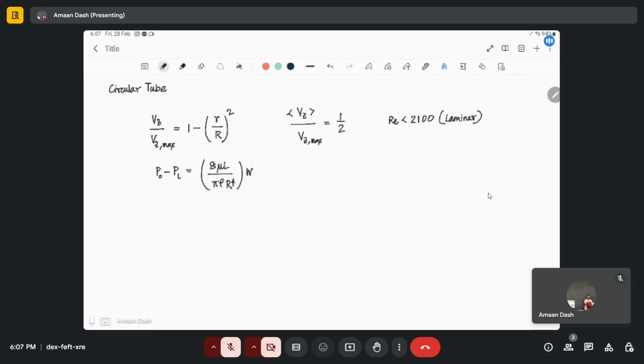But for turbulent flow, the velocity is fluctuating with time at each point in the tube. If you remember, the laminar case is a kind of parabolic profile. But for turbulent flow, we will not be having such a smooth profile; rather, it will be a fluctuating profile. And therefore, how do we obtain an expression for such velocity?